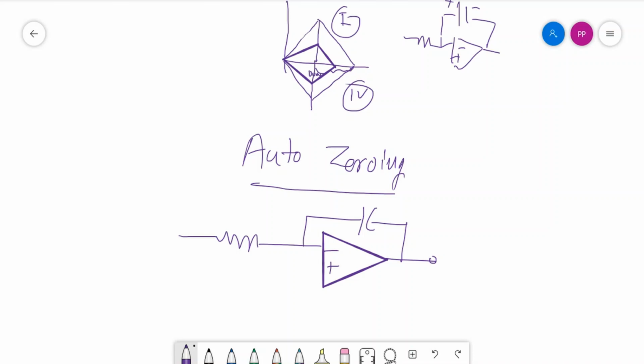will be developed on both the plates of the integrator but with opposite polarity. So you have the V in for charging. Here the charging happens in this way, so it becomes positive, this is negative. So this is the selector switch. Once it is charged, you can discharge it through a grounding circuit. Once it is grounded, the positive plate will discharge quickly through this ground path. So that is how the auto zeroing circuit works.